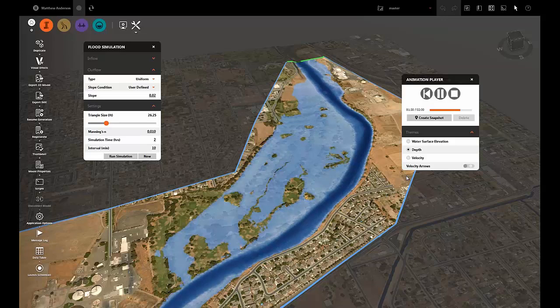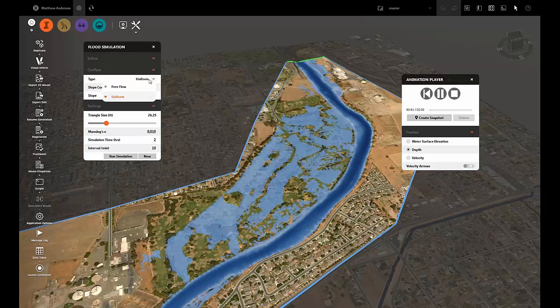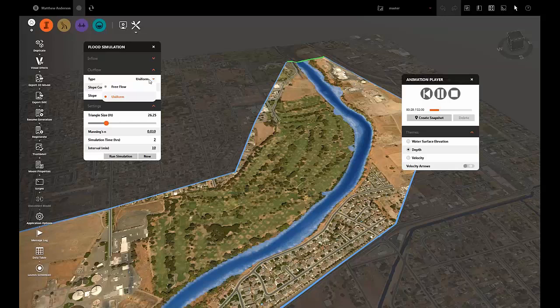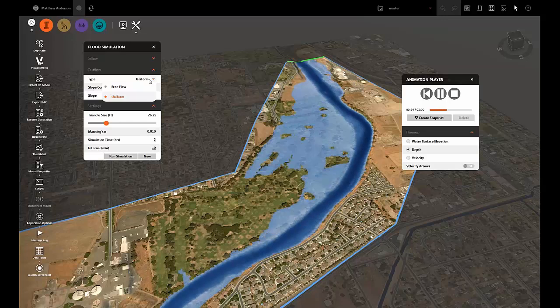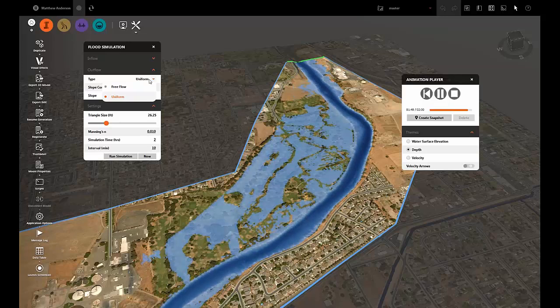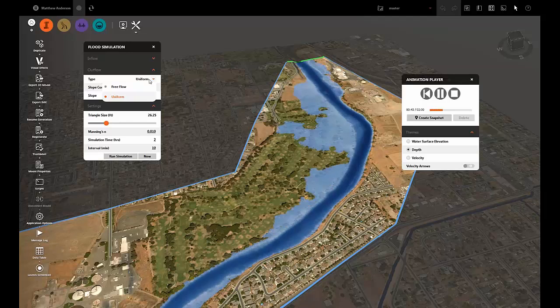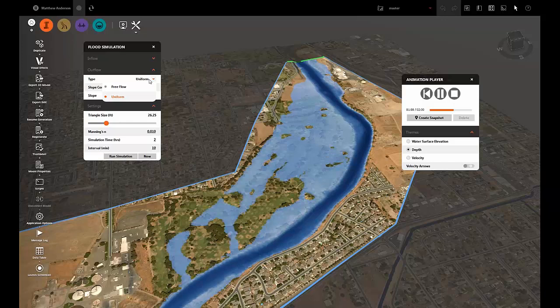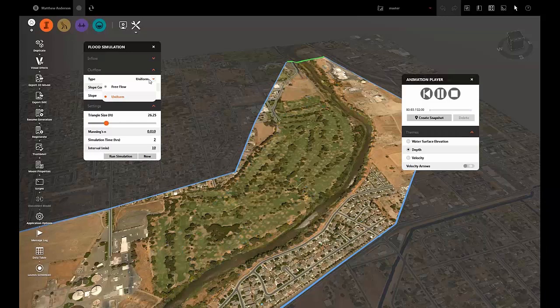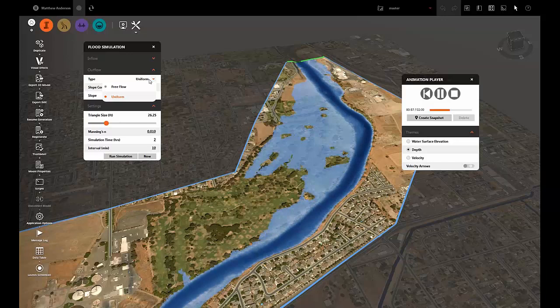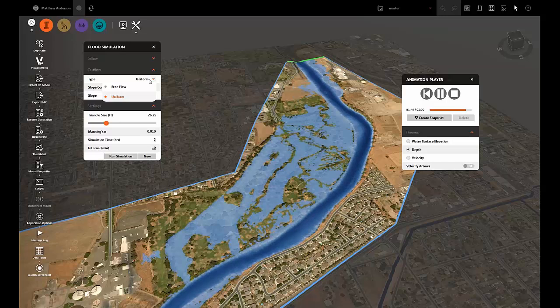Yeah, the free flow is actually a condition where the discharge, or the volume of water that approaches the outflow boundary, is just let go out of the boundary. It's called free, although it's not totally free, but it's a less restrictive boundary condition where the water is just let go on the boundary. There is no other relationship imposed there other than that in general from cell to cell.